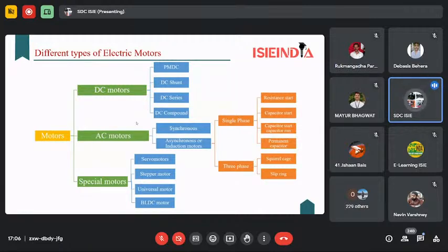A special motor is designed for special functions or special purposes, and comes with fewer disadvantages and special techniques, like a servo motor, which is used for precise angle of movement, like in a robotic arm, and a stepper motor, which is used for sequenced movement, laser cutting and 3D modeling. A universal motor has a special technique in that it works on AC as well as DC power.